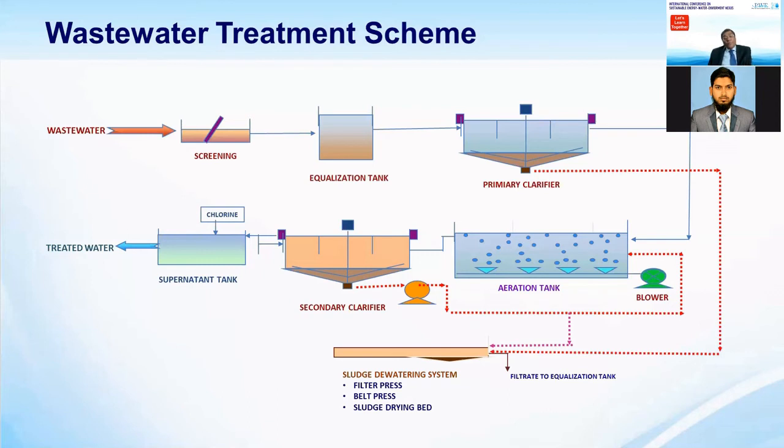Here, if we assume that all the processes of a batch complete in 8 hours, then we will design the equalization tank for at least 10 hours, giving a 2 hour margin so that if you repeat any process, it can be homogenized, because the equalization tank gives a constant feedstock and characteristic flow to the next treatment stage. Basically, the equalization tank is the buffer tank which handles the flow fluctuations and contamination fluctuations of your incoming streams.